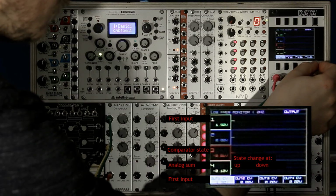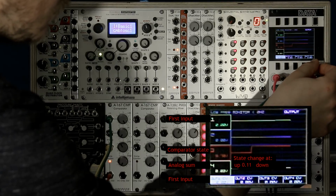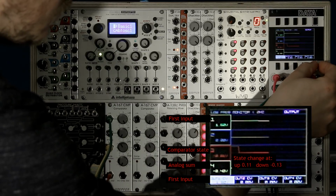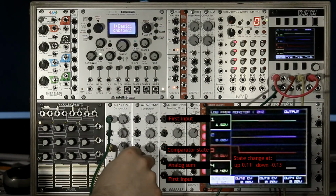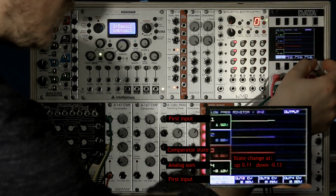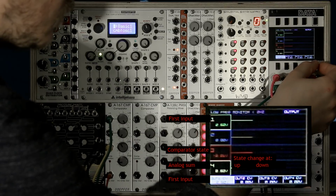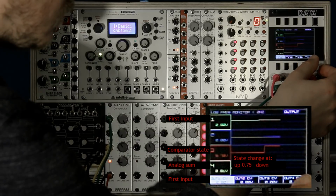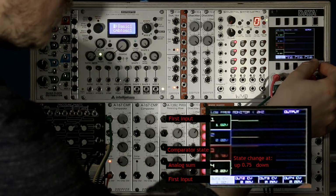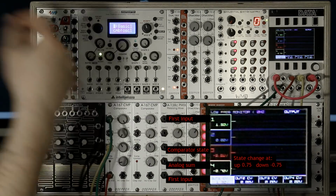So we are now at 0 volts and the state changes at about 0.11 volts at some output. Let's go down. It changed at -0.13 volts. This is called a gap. To make it more obvious, we can increase the gap control and do the same thing again. Now it changed at 0.75 at some output while going up. And it also changed at -0.75 when going down.